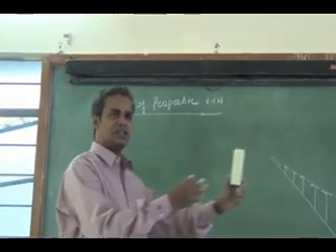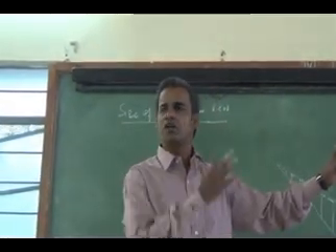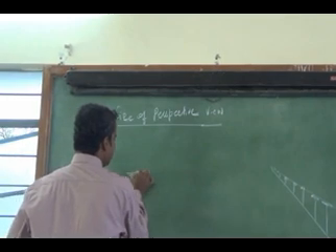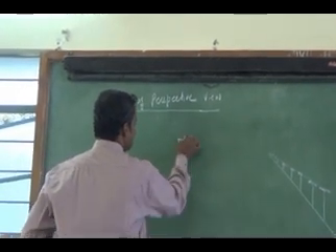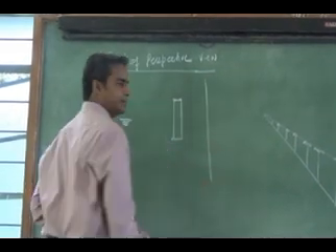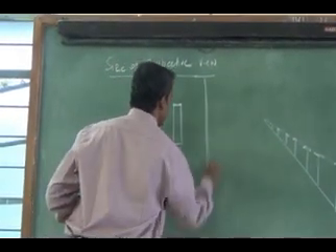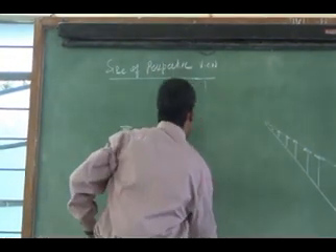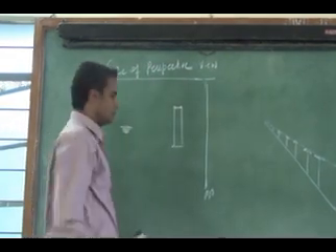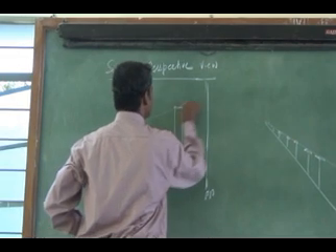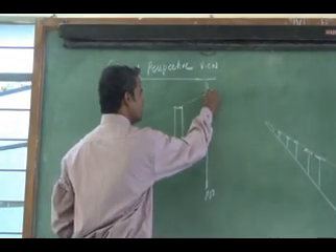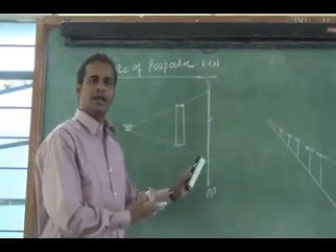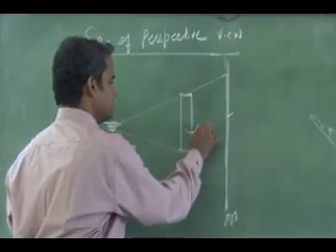You know perspective is nothing but the normal ordinary projection, not an orthographic projection. The normal ordinary projection is nothing but the perspective projection. So I have the observer's eye, and I have the object. The picture plane I will have somewhere here. I am capturing the image on this picture plane, drawing the perspective on it. What will be the size of the perspective? It is the ordinary projection, so here I am going to draw the perspective view. What will be the size of the perspective? Enlarged.